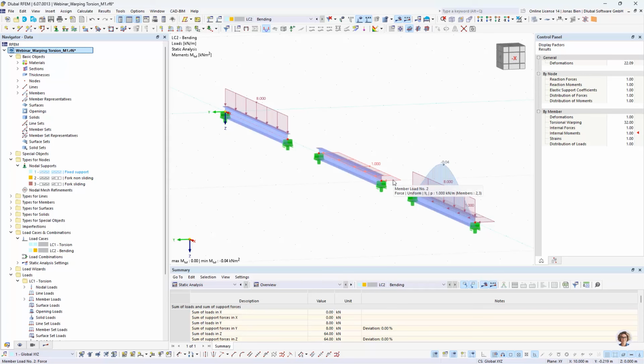And I don't want to make you nervous and say that always in the case where you have double bending, it has a critical influence on the design. I just want to raise the awareness that if you have double bending or biaxial bending, there is probably, at least if you are working with non-warping-free sections, some indirect torsion that is generated by this loading condition.